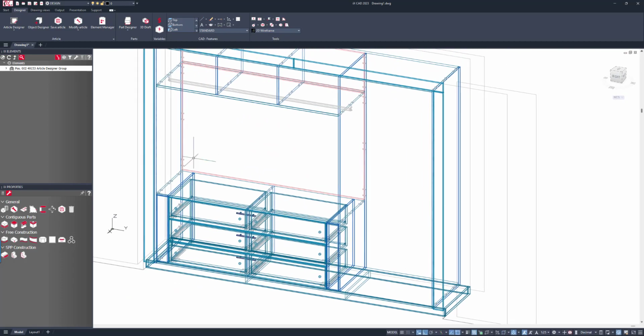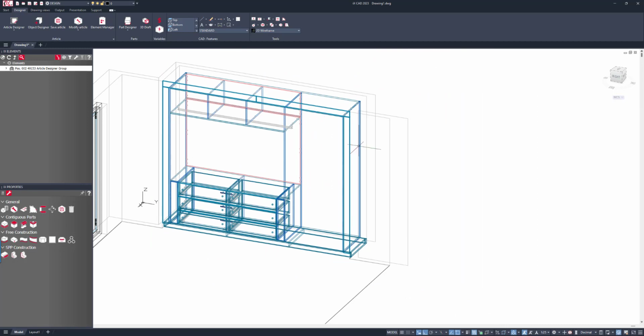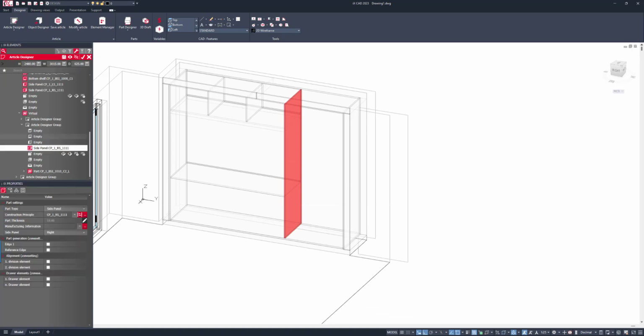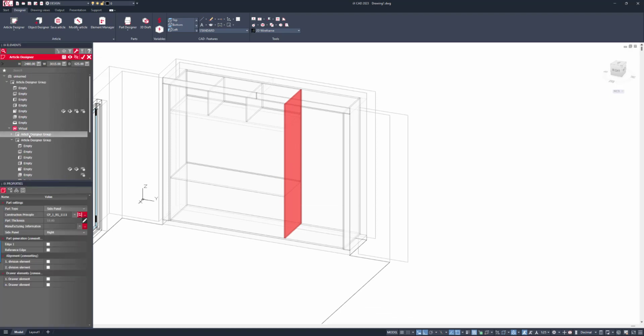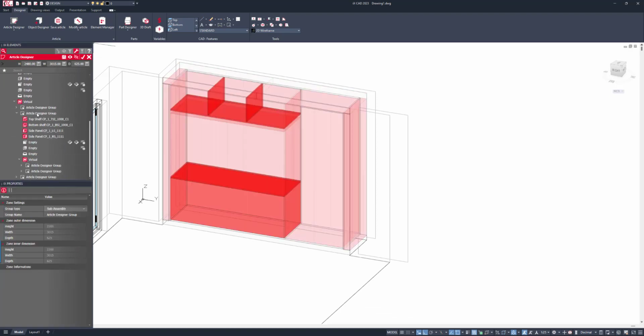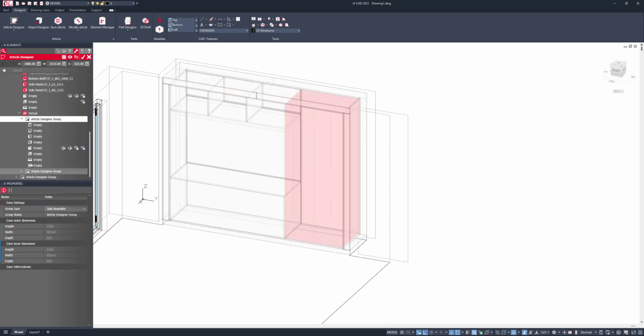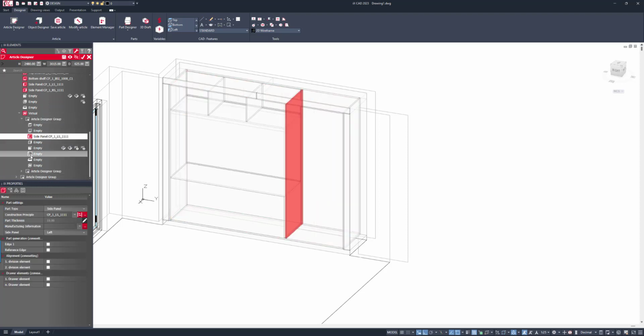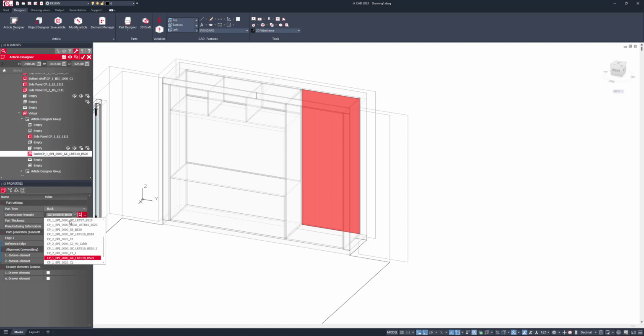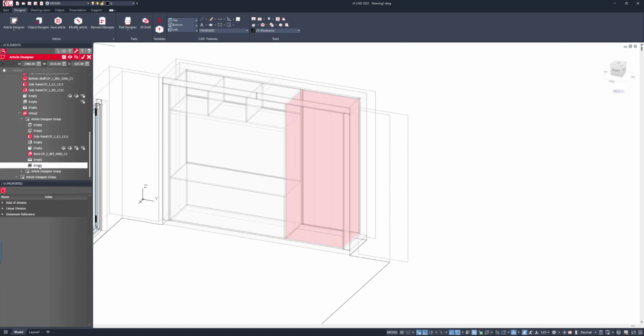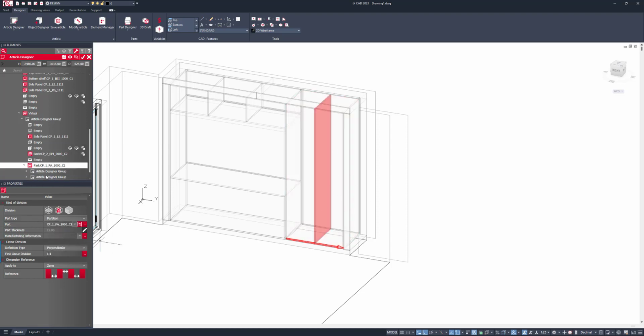Okay, so next thing that I want to do is this right hand side over here. So I'll modify that and click on my partition again, and then go up to the level where I have my divider. Once I've opened this up, I need a left hand side, I need a back panel. I'll change that back panel to be my back panel of choice. I'll go in and add in a partition. We'll divide this again equally with a linear division of 1 to 1.